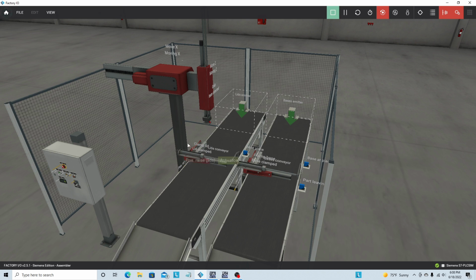But if something is in the extended position on the initial scan of the PLC, we're going to have to do something to tell it to come back to the home position. If it's in the home position, we can't drive our output and set this bit. It's kind of a catch-22 that's with it.